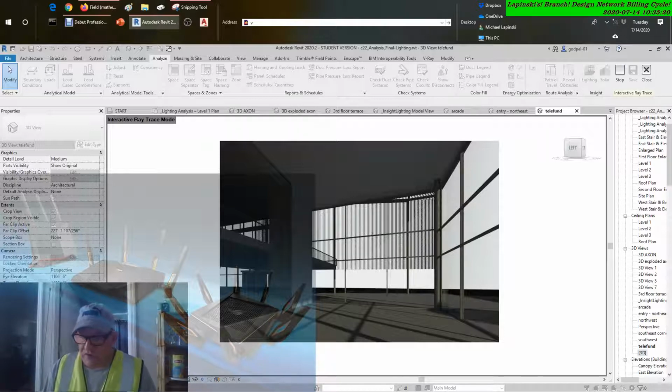The box is unchecked by default, but checking it will tell Revit to use the thermal properties associated with materials you have in your model. For our analysis, we have no materials assigned, so we'll leave this unchecked. But if you are performing an analysis on a more developed model, this option could give better results. Be aware that you will need to make sure to have thermal properties assigned to each of your materials to get accurate results. Once those values are set, click OK to exit the dialog box.